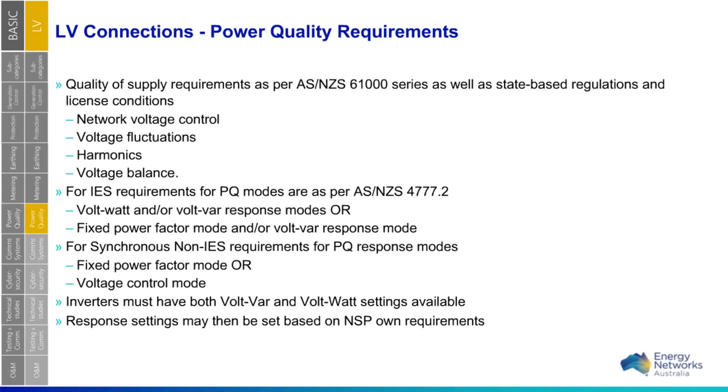The power quality requirements for LV connections will be primarily based on 4777 as well for IES, which is volt-var response mode, or fixed power factor mode with volt-var response mode. And then for non-IES, either using fixed power factor mode or voltage control mode. And just reiterating here that inverters must have both volt-var and volt-watt available, and that the settings would be based on what the NSPs recommend.